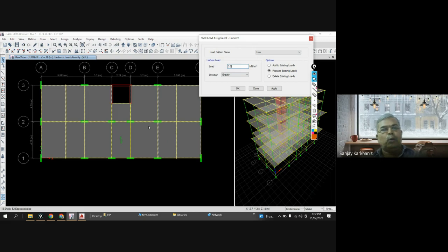That is called a roof. In that case, we don't call it a terrace, we call it a roof. So if the roof is not accessible, then code says that you may consider 1.5 as live load. But if it is accessible, then it should be considered as 2. That is what code says.